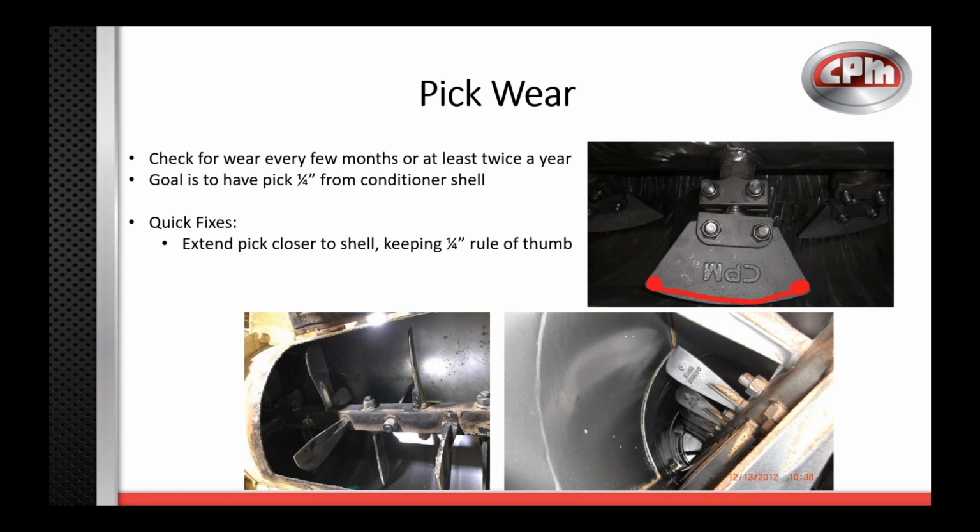Now the bottom pictures, those picks have probably been used for quite some time, and that's what we call significant wear. There really isn't any chance that flipping these around is going to do much good, so we would recommend that these picks be replaced.